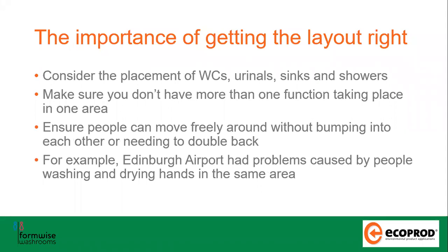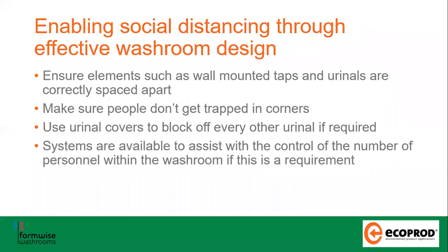Consider the layout of WCs, urinals, sinks and showers, if showers are included. Make sure you don't have more than one function taking place in one area, and then make sure that people can move freely around without bumping into each other or needing to double back. And just that point at the bottom there, that was a live situation where a high footfall location created problems by more than one operation happening in exactly the same area, which they've now changed and addressed.